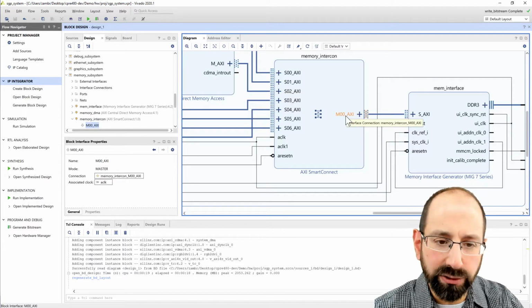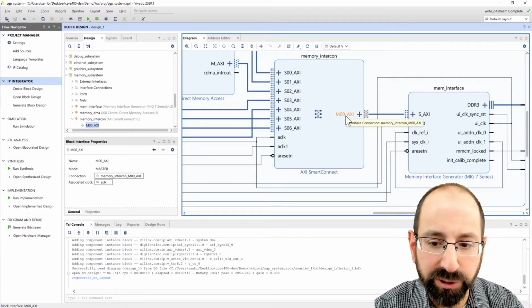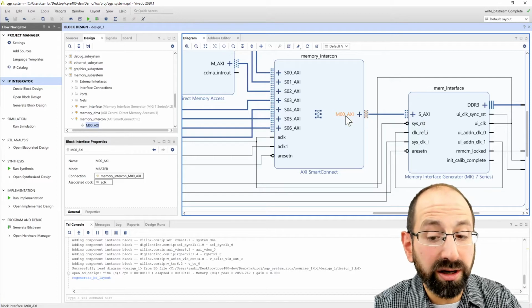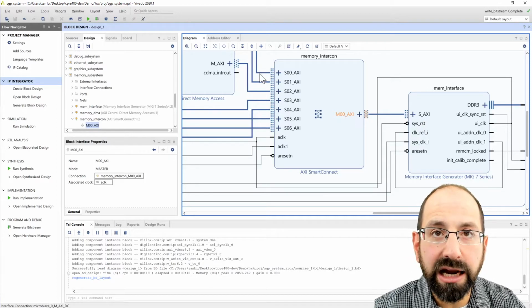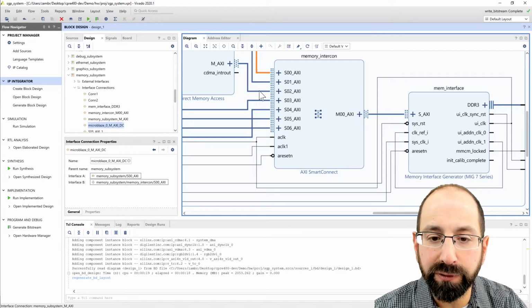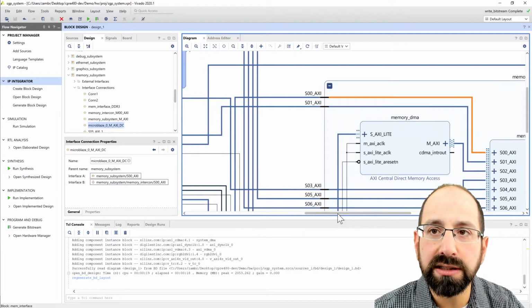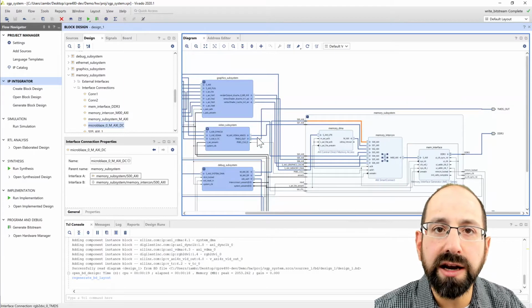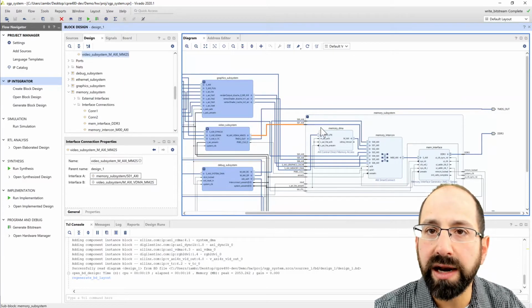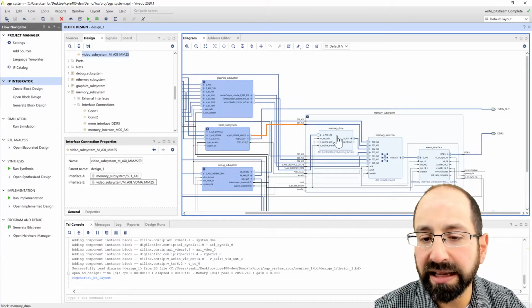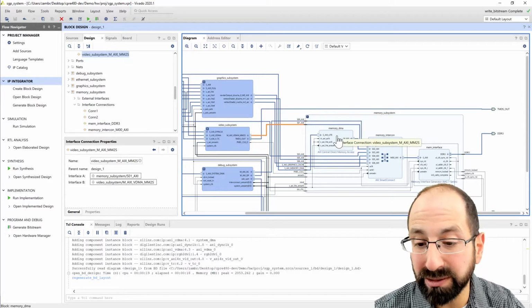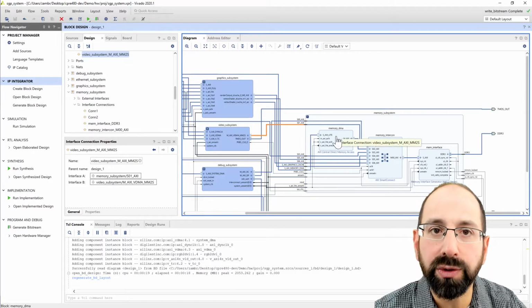And we talked a lot on Tuesday about, from the frame buffer's perspective, that arbitration is pretty important here. If we look at the various connections to our memory, of which the frame buffer is the primary purpose of having our memory in the system, one of those connections is going to then connect back to the video subsystem. It's this one actually right here. One of the connections is just a DMA. If we want to do some block memory transfers, that's one way to do it.